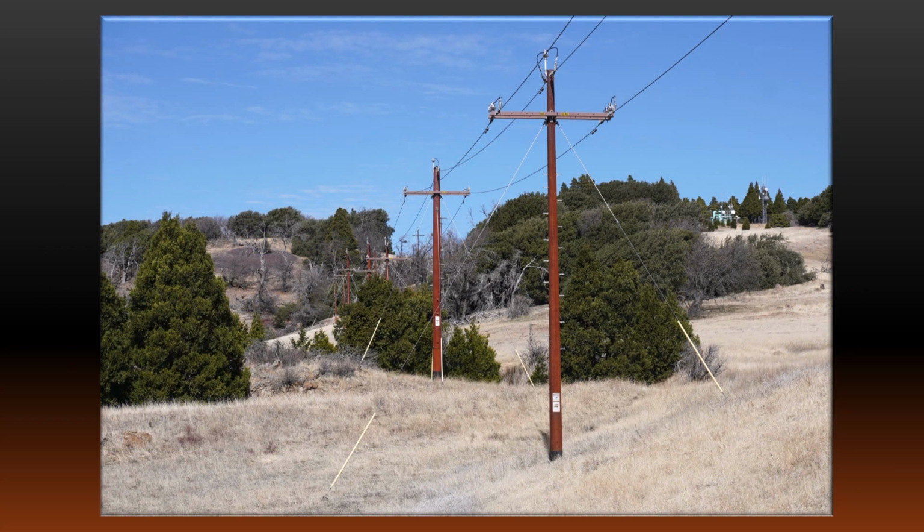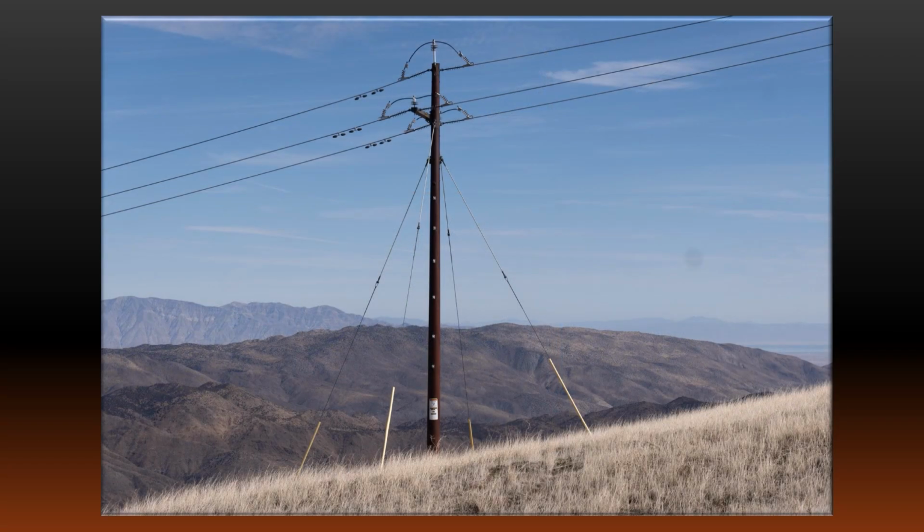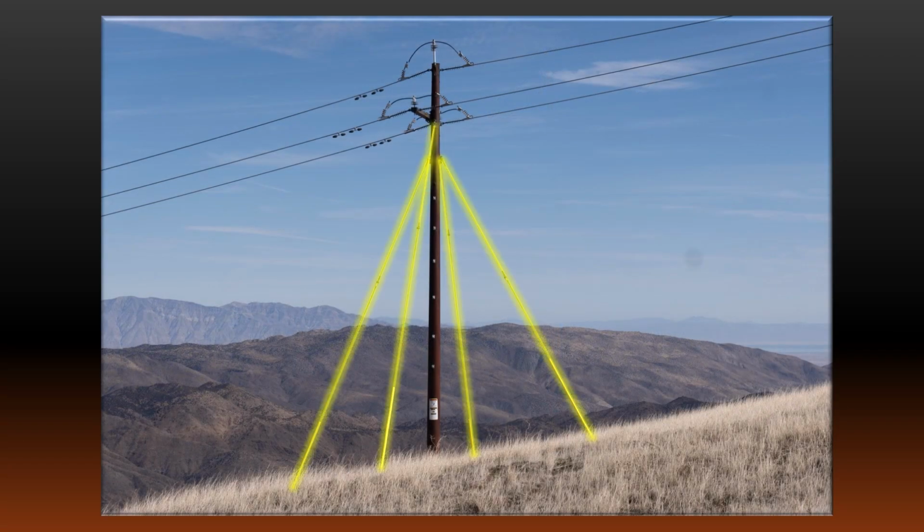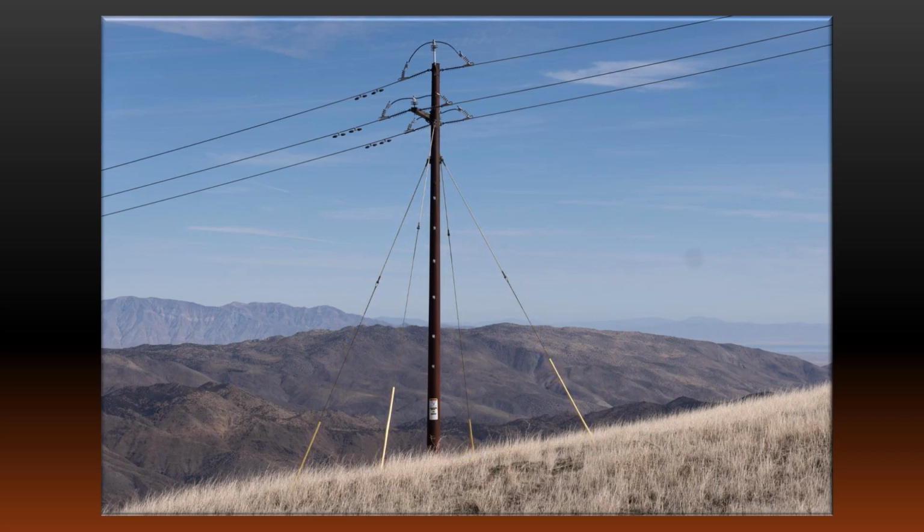Here's an example of a pole installed in an extreme loading district. Because of the very high wind loads applied to the pole and the conductors in this area, wind guys have been installed on this pole. You can see them here. They've been installed to stabilize the pole from the forces applied in the transverse direction. Here's another one. This one has wind guys installed in both the transverse and longitudinal directions. This is also a Class H1 pole built to withstand the extreme wind and ice loading at the top of this mountain.